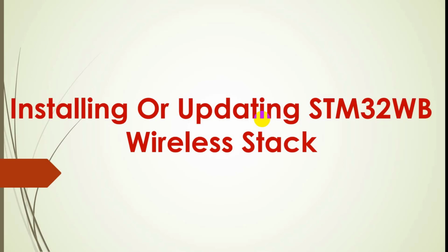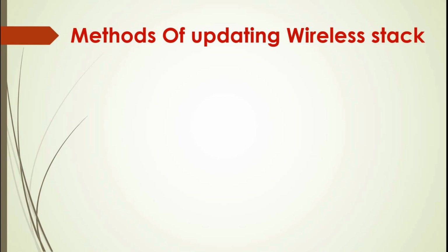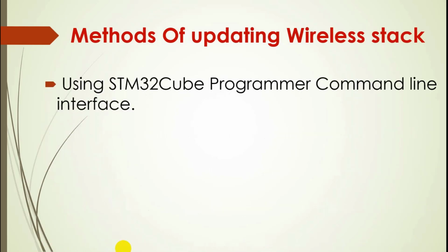Today we will talk about installing or updating the STM32WB Wireless Stack. So let's get started. Let's see what the different methods of updating the STM32WB Wireless Stack are. You can update your wireless stack using the STM32CubeProgrammer command line.